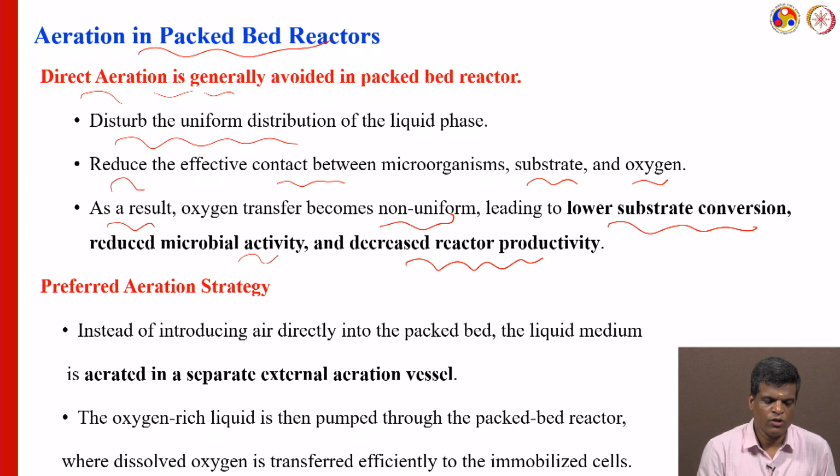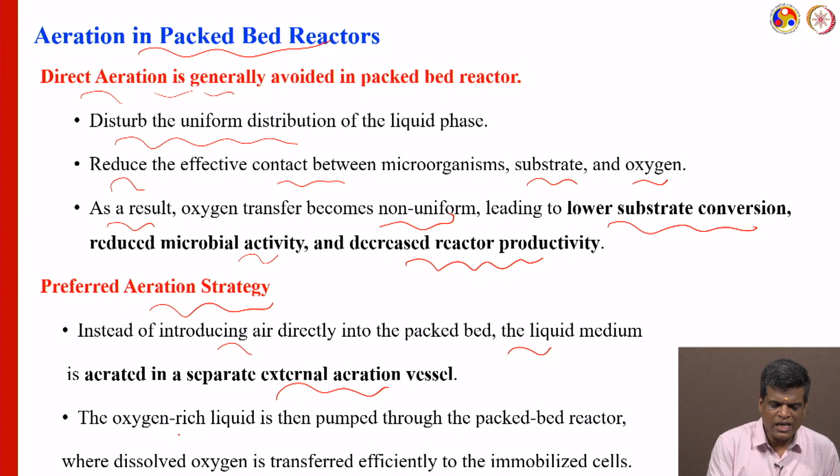So we always go for the preferred aeration strategy here, because instead of passing air directly to the packed bed, you can use a separate external aeration vessel, and we can do the aeration there. The oxygen-rich liquid is then pumped through the packed bed reactor, where dissolved oxygen is transferred efficiently to the immobilized cells. That is one.